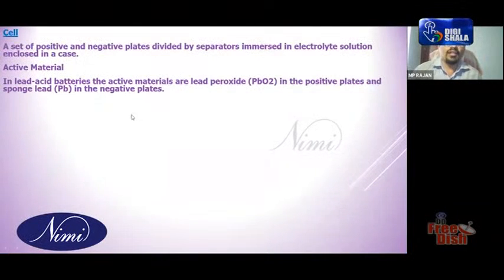So a cell is a combination of many positive plates and negative plates divided by separators, as we have seen. And active material means the material which is used to make the positive plate and negative plate. What is your positive plate? Lead peroxide or lead dioxide, and this is chocolate color. And the negative plate is pure lead, that is in gray color.